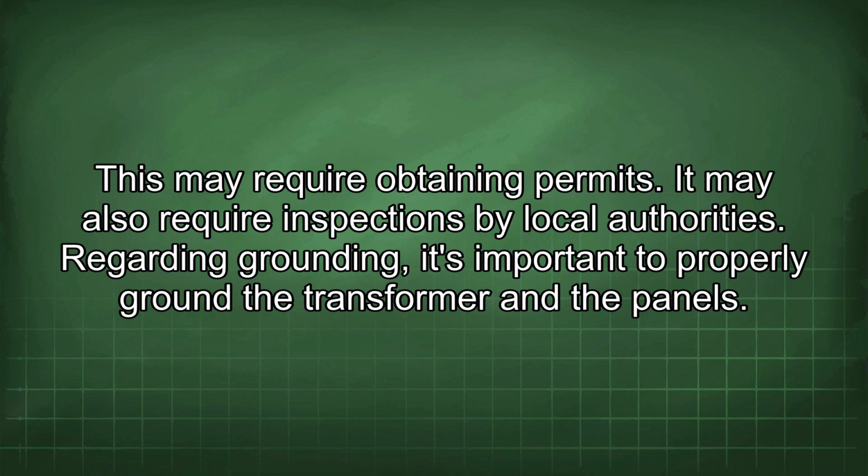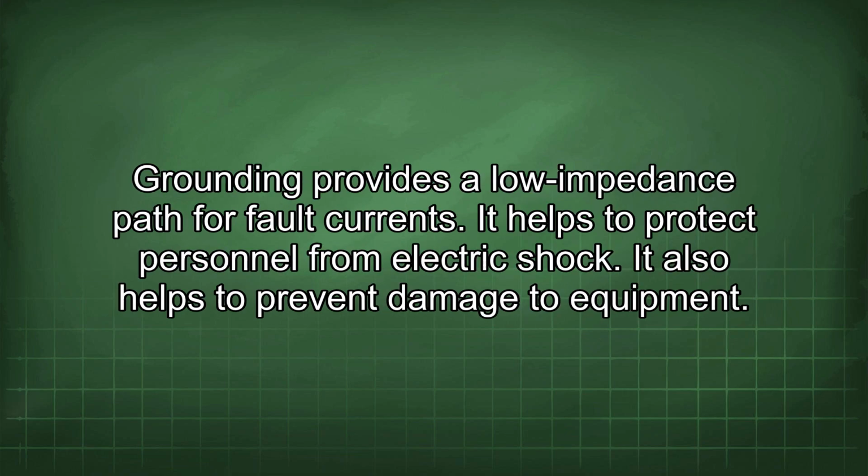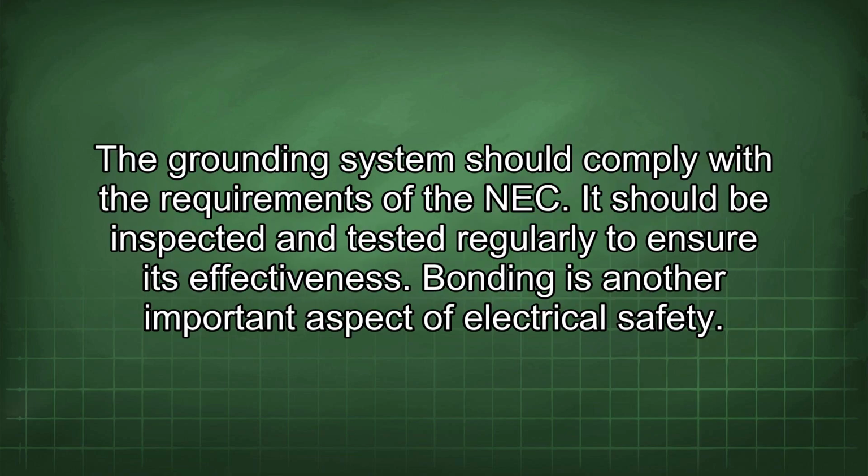Regarding grounding, it's important to properly ground the transformer and the panels. Grounding provides a low impedance path for fault currents. It helps to protect personnel from electric shock. It also helps to prevent damage to equipment. The grounding system should comply with the requirements of the NEC. It should be inspected and tested regularly to ensure its effectiveness.